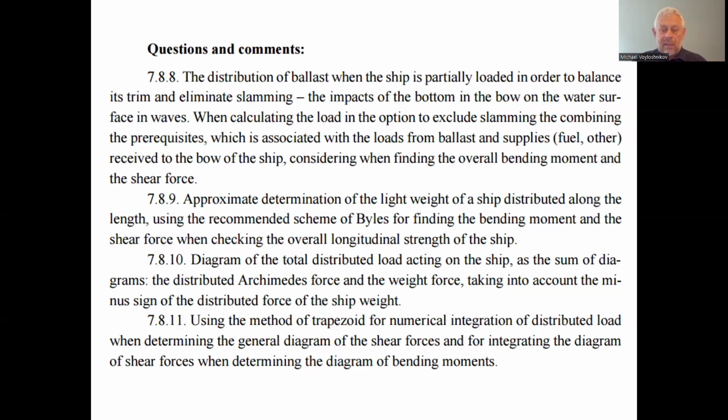So if we do increase the bending moment and shearing forces by the adoption of the ballast to exclude the slamming, this increases, on the other hand, the bending moment and shearing forces on the calm water. This increases the forces we next use for the checking of the general strength of the ship hull.